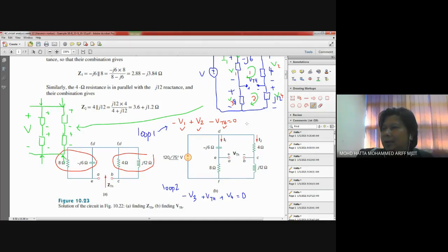And comparing this first equation and this second equation, basically you don't need to work out the KVL using both equations. Only use one equation, but you can check your answer using the other equation. It should give us the same value. If you calculate your VTH using this loop, maybe let's say this VTH equals 10 with the angle of 0 degrees.